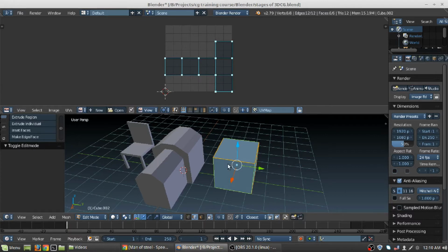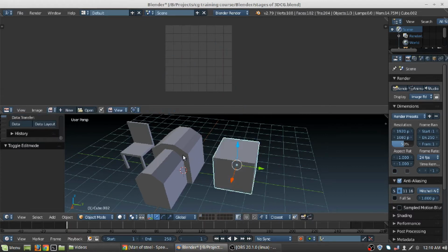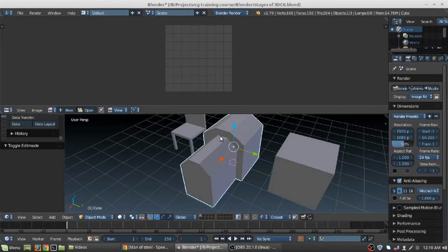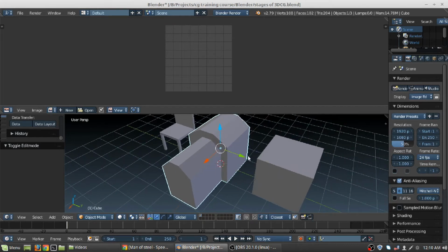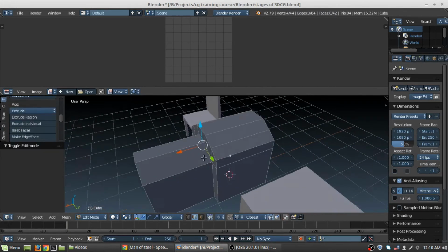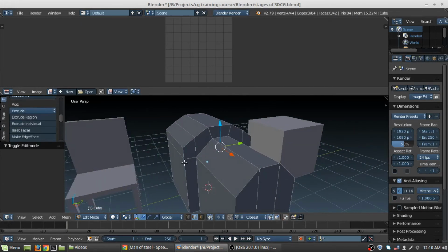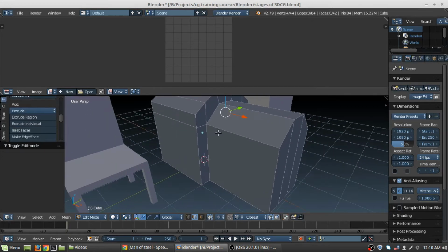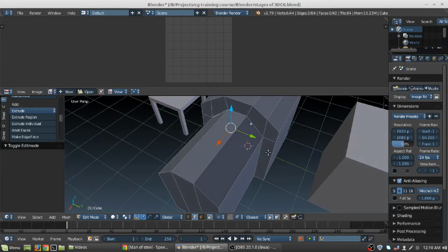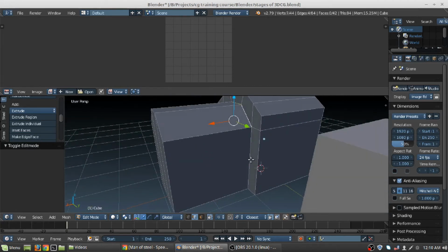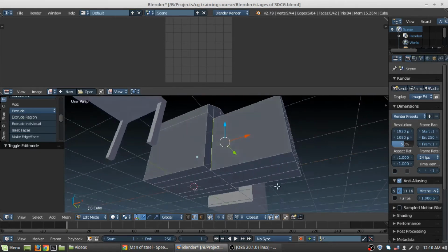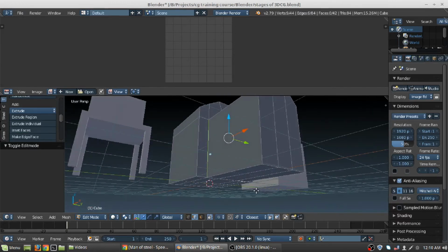Never mind. Okay, now moving on, the next object, which is slightly more complex than a simple box, and let's just see how we can unwrap this. We will go into the edit mode by pressing Tab and then select the edges that we think should be selected for unwrapping these UVs.